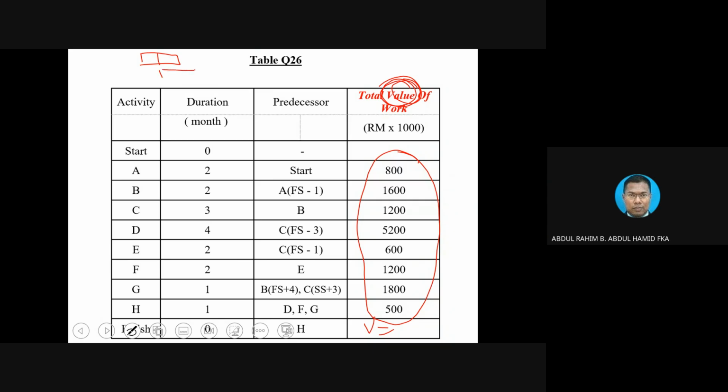So this is B. Okay, this is A, this is B. And then C is connecting from B. Since we already have B, this is the first month, third month, this is C. You see, now you already construct the bar chart very quickly. But of course, you need to practice how to interpret this data and construct the bar chart quickly, instead of coming up with this PDM diagram that will take you forever. I mean, if you make a mistake, it is even worse.